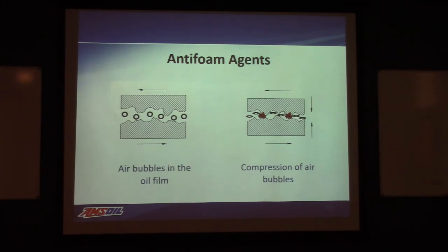Now that oil film collapses, and the likelihood of metal-to-metal contact now exists. So you don't want air in there for that reason. Also, that air contains oxygen. These air bubbles are now exposing a greater surface area of the oil to oxygen and increasing the risk of oxidation and hence deterioration. You don't want that to happen.